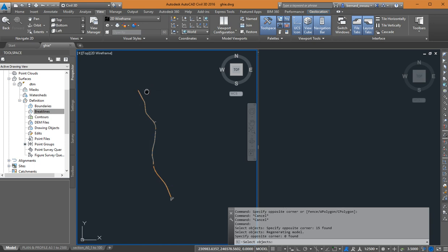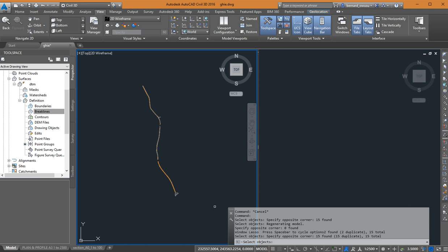To draw the window, some people drag it. No, don't drag it. Just click one edge, open, then come and click the other edge. Okay, when we finish this one, we'll go back.